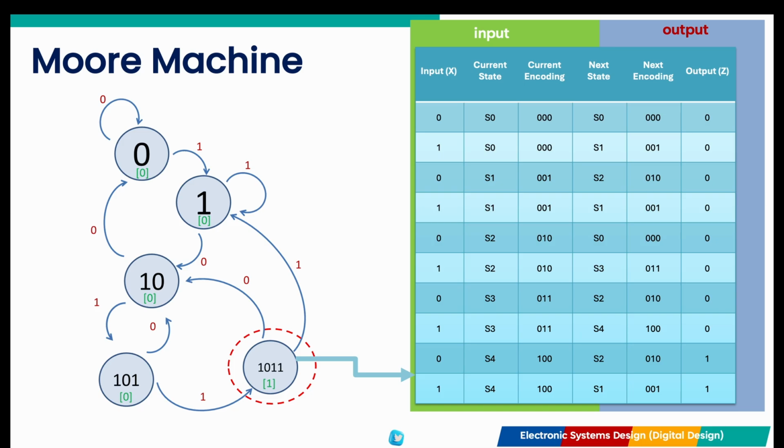It only cares that the success state has been reached. Take note that every input state combo has a defined destination. The output column only changes when the current state changes. Now that the table is complete, we are ready for the Verilog implementation.